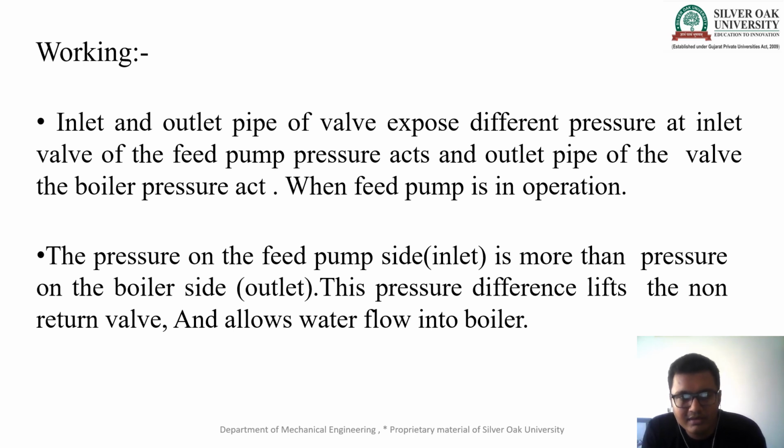When the feed pump is in operation, the pressure on the feed pump side, the inlet side, is more than the pressure on the boiler side, or we can call it the outlet side. This pressure difference lifts the non-return valve and it allows the flow into the boiler from the outside source to the inside, that is the boiler.